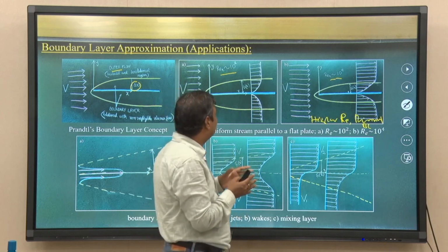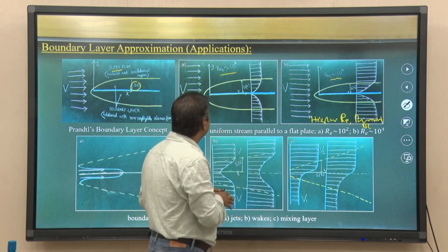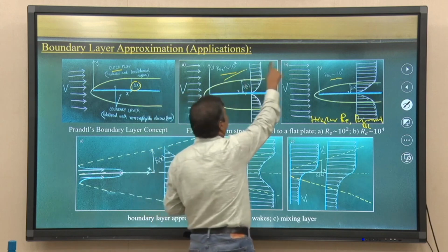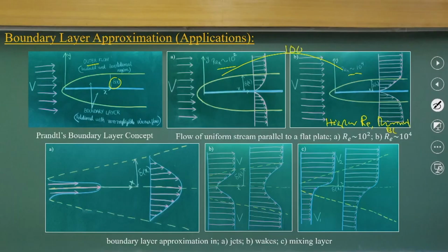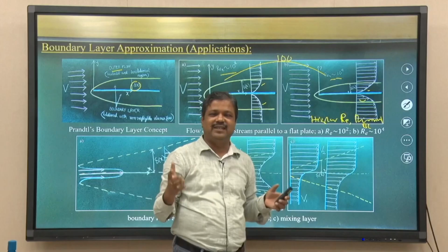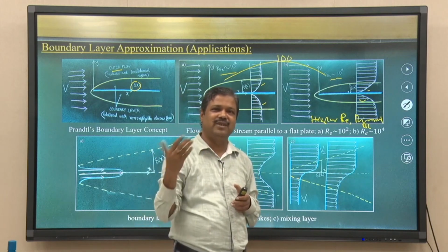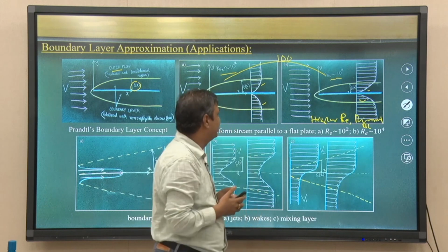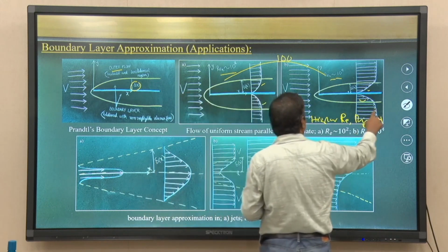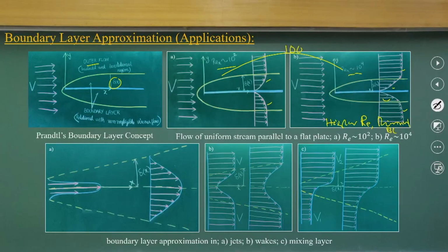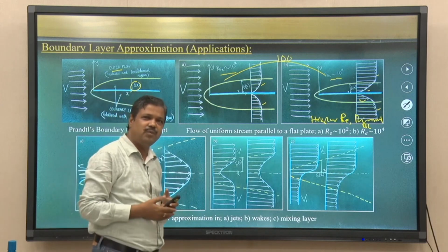So, that is what we can also see experimentally: when you change the Reynolds number, the thickness will decrease almost 100 times. Here I again emphasize, just look at the velocity distributions. Because of the different Reynolds numbers you will get different velocity distribution profiles, and beyond these outer regions the velocity will be more or less constant, because it has reached 0.99 of u, the free stream velocity.